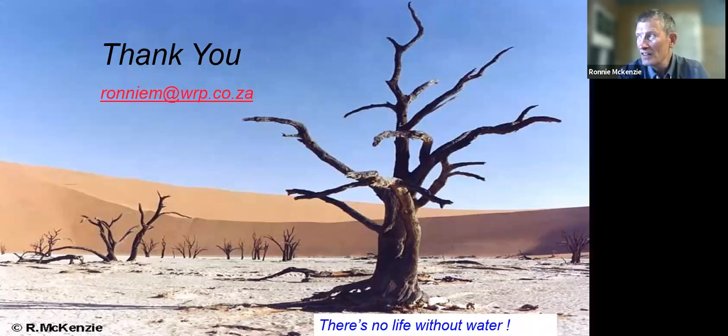In our experience, where we've had problems with certain companies slamming open valves and slamming closed valves, and it works its way back into the reticulation system, we often find that the PRV is quite a useful, almost dampener of certain water hammer effects.